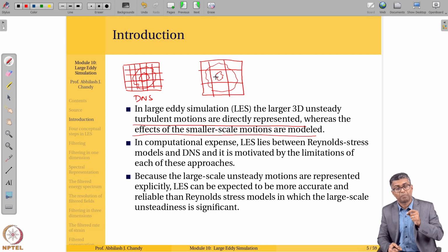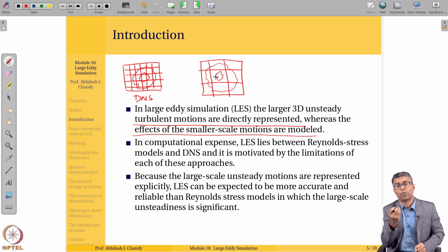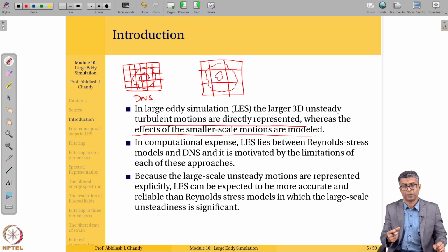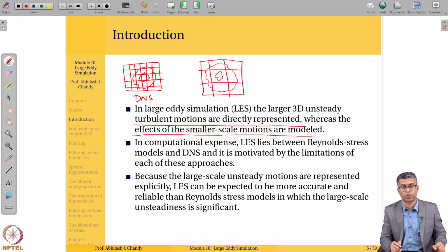Now here, mathematically, the subgrid scale model comes about in an effort to close some unclosed terms that pop up when you filter the Navier-Stokes equations. Let me repeat that. You have the Navier-Stokes equations. When we filter that, there are some additional terms that are going to pop up. Those are the residual terms that account for these small scale motions that I have drawn.